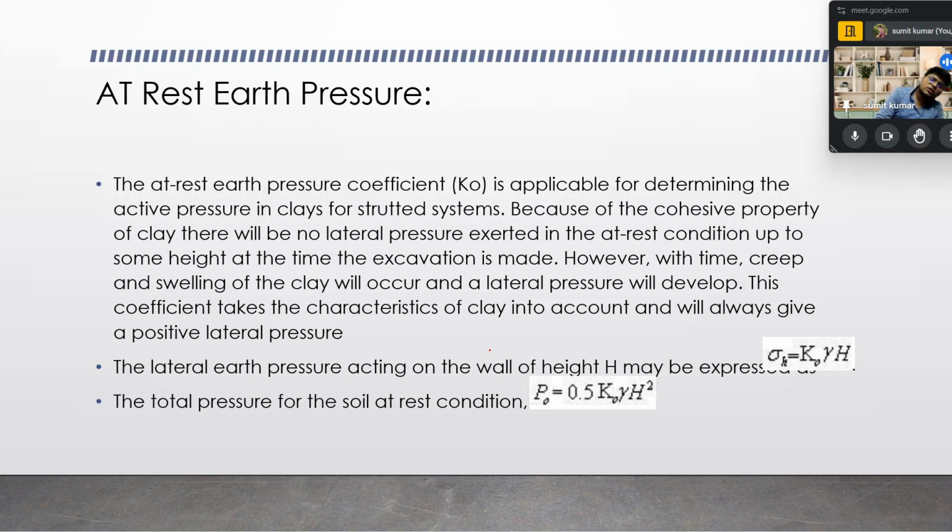There will be no lateral pressure exerted in that condition when it is at rest, and it is also up to some height at the time the excavation is made. However, with time the creep and the swelling of the clay will occur and a lateral pressure will develop.